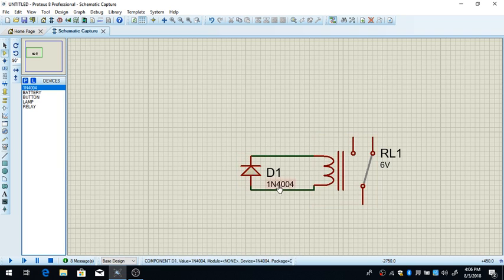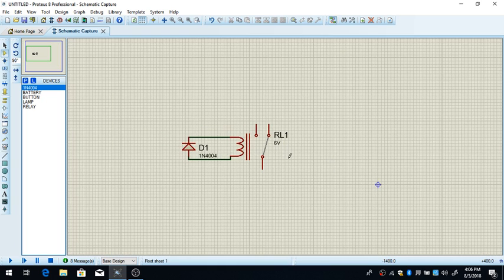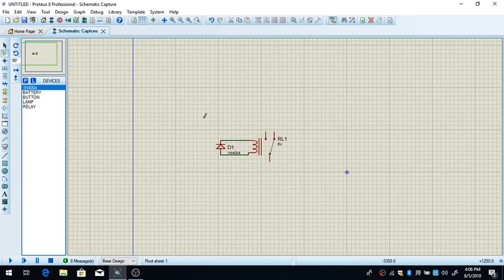It won't. It's not going to break itself. So it's really a good thing to always put a diode in parallel with the coil. But it's kind of hard to explain because I need diagrams, graphics, and all that, and I don't want that much education in this tutorial.